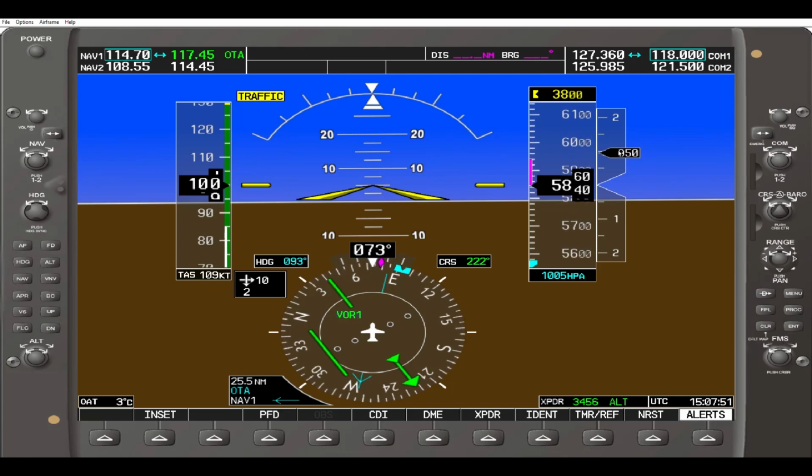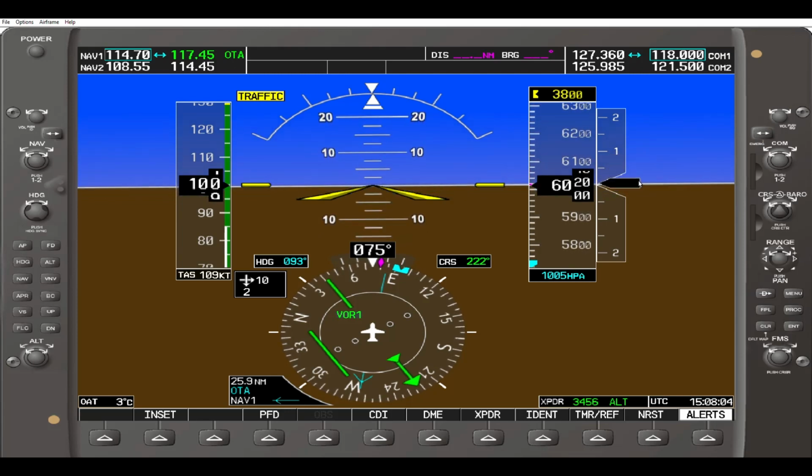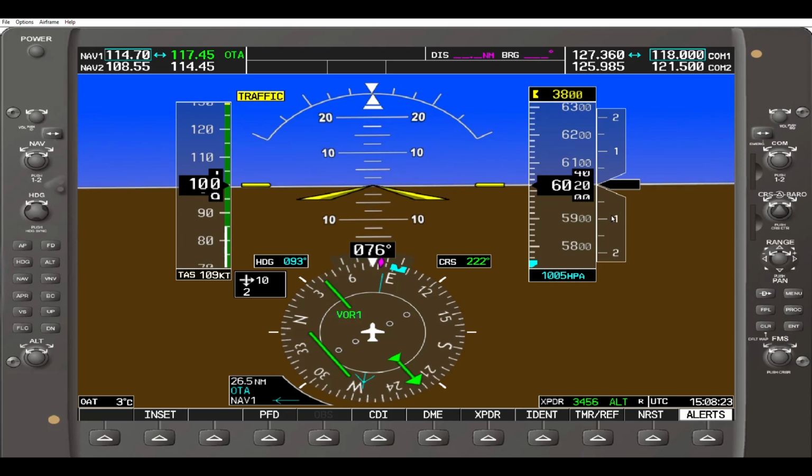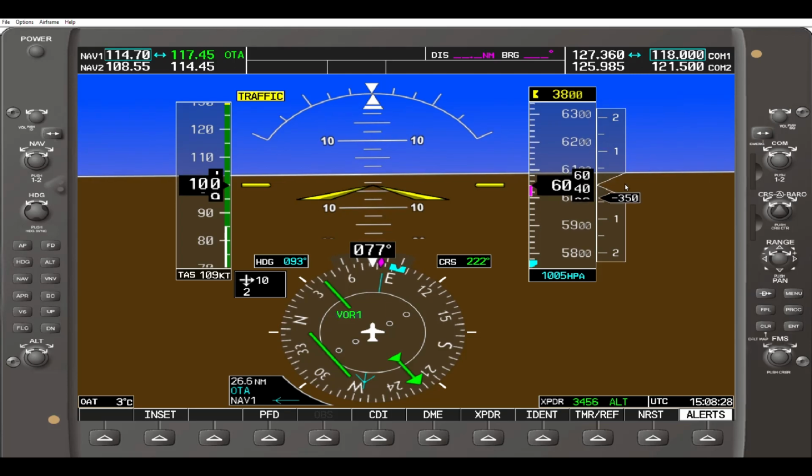If we're climbing, this is our rate of climb, 950 feet per minute. If I want to level off and not climb nor descend, basically I put the vertical speed indicator needle exactly inside this triangular opening. I match it up. You can see there is no number here, so when the airplane is not climbing and not descending, there is just simply a black needle, there is no number, and as we gain some vertical speed, there appears a number and we start climbing or we start descending.